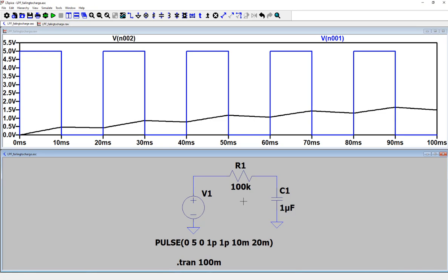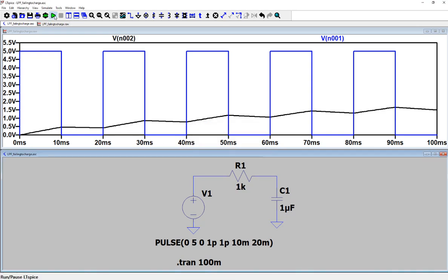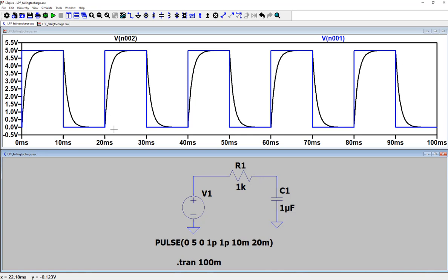You still remember how it gets fully charged? What that looks like? Okay, so this is considered fully charged, even though it's not good, but it's charging up to 5. So your output is reading 3.3 volts, even though here it is 5 volts. I just say 5 volts logic, okay? It's a 5 volts digital signal. So at least it's getting you 0 and 5 volts. So if this is a digital output, you are getting 0 and 1s. So you're not losing your data, right?